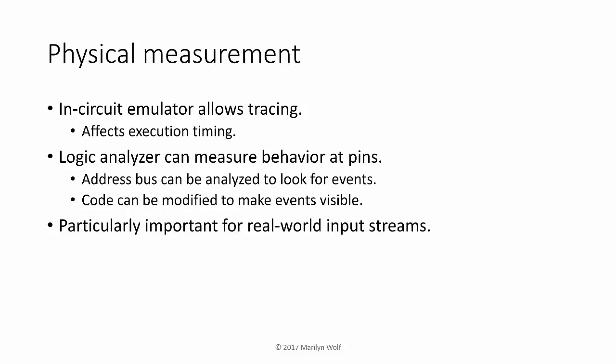We can physically measure performance using techniques such as in-circuit emulators or logic analyzers. In the case of a logic analyzer, we need to be able to see events on pins. Physical measurement can be particularly important for real-world input streams in which it's difficult to generate realistic data, and the only way to exercise the system on real data is to plug it in.